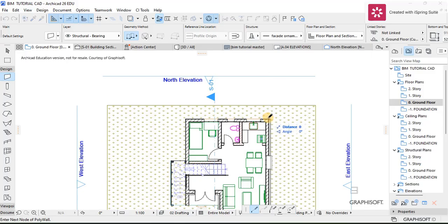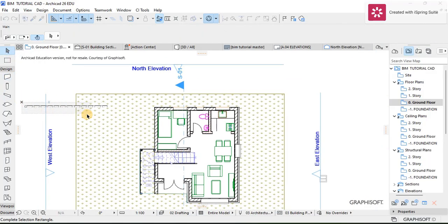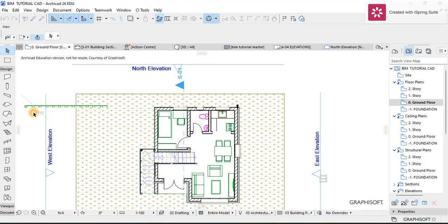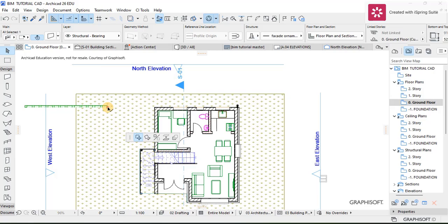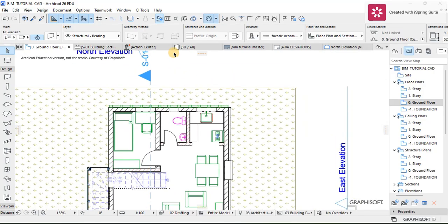Let's make sure it's a bit thinner. Let me tab it and then make it like 150. So click, and then I'm going to drag it back to my wall now. When you're drawing a complex profile, it usually draws itself further away from where you want it to draw. So what you're going to actually do is just drag it to where you want it to be. So let's see how things have come and see if they are actually okay.